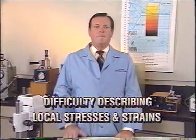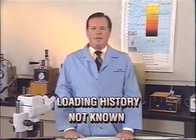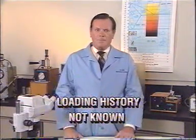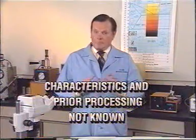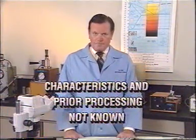Difficulties in predicting fatigue life arise from the inability to describe any one of various factors. When it is difficult to describe the local stresses and strains, when the loading history is not known, and the fatigue life characteristics of the material, its heat treatment, and prior processing are not known. To estimate the fatigue life of components or assemblies, the designer is also required to rely on experience with similar parts and must eventually depend upon qualification testing of prototypes or production parts.